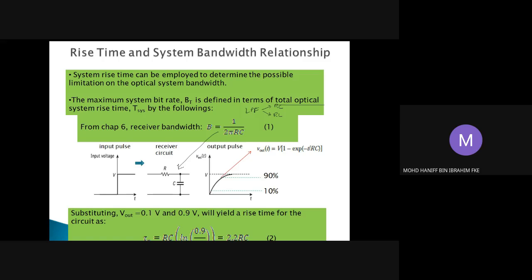In this particular case, we're using the RC circuit for the low pass filter, where the output voltage is measured across the capacitor. If you can recall, for this low pass filter circuit, the cutoff frequency omega C shall be equal to 1/RC.